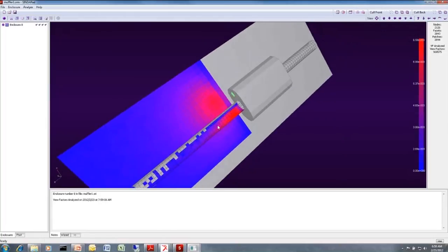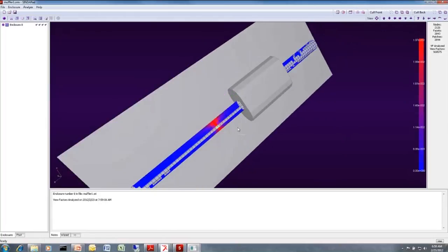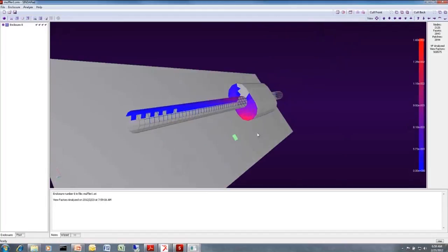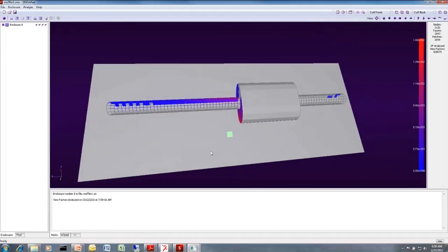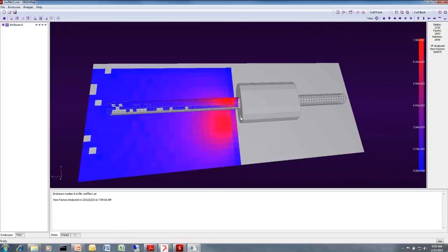So I can just double-click on anything and see from that surface how well it sees other things. And this is especially important if you have some electronic equipment you're trying to shield from something hot. You can just play around with your geometry and see what can see what, and if the shield's working or if there's something hot that has a good view of something that you're trying to protect.